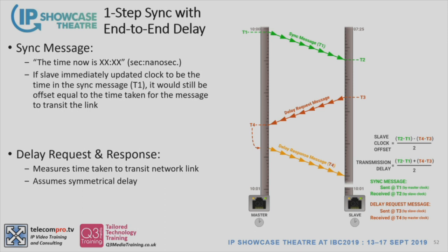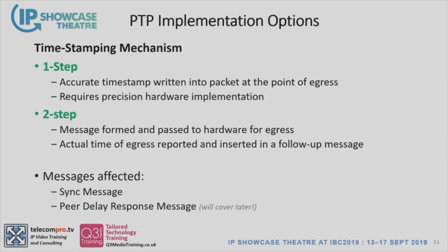So these delay request and response messages are key to what we call the end-to-end delay mechanism. Now, that whole process started with that sync message, the time is 12 o'clock, being sent in a message. If we're a software-implemented PTP master, we format a message and put the timestamp of 12 o'clock in it, then hand that over to the hardware layer to put all those extra IP wrappers and MAC layer wrappers on it.